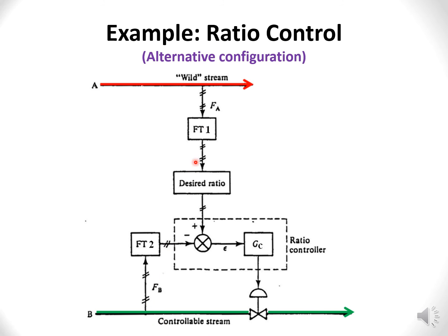So what happens normally, we prefer this system, because this is talking about just flow. This desired flow, actual flow. Normally the error is not so hectic or erratic, not so much instability in this sort of system, so it can still be handled. So this is the more preferred way of executing ratio control strategies in the real world.